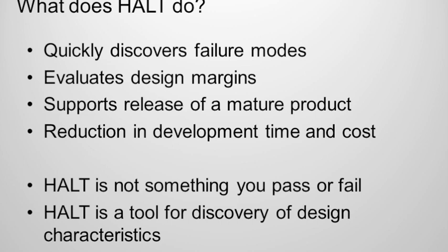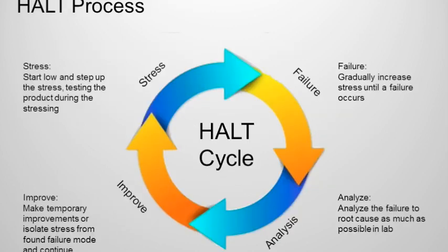So let's take a quick look at the process itself. There are 4 clear sections of the process. You're going to stress the product. You're going to do this in incremental steps. You want to start off with lower stresses and be getting good response and functionality of the product, and continue to increment it because you want to see how its performance changes as you're incrementing the stresses.